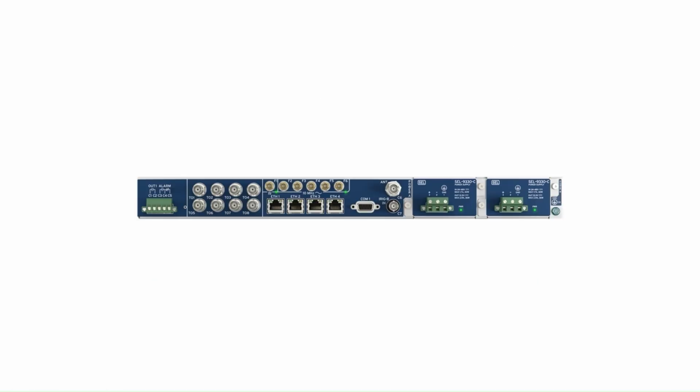So physically what that's going to look like is we'll have our PPS coming out these BNC connectors, T01 through T08. We'll have our 10 meg reference coming out these SMA connectors, F1 through F6, F1 being a square wave, F2 through F6 being sine waves. And we'll have our network connection doing HTTPS and NTP on Ethernet port number 1.